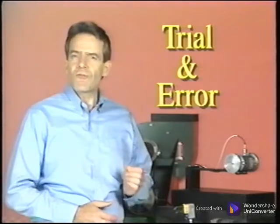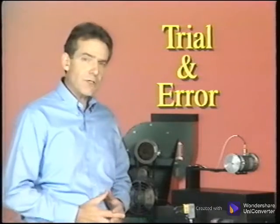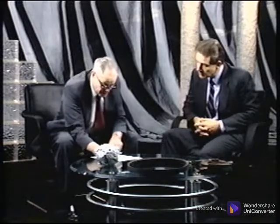These structural modifications affect your plant's machinery in the same ways. However, using a trial and error method for making modifications often leads to an incorrect solution. Lots of people have increased stiffness and at the same time increased the mass and wondered why the frequency didn't change. If the stiffness increases and you add mass to do that, you really haven't done much to the natural frequency. Before making permanent structural changes to a machine, it is often recommended that a modal analysis and/or a finite element analysis be performed.